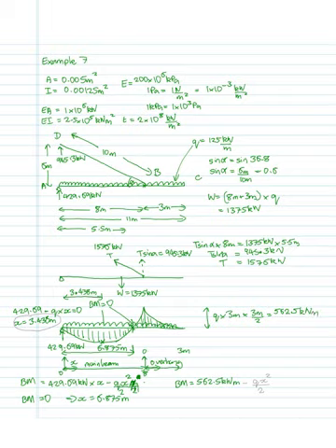So there should be a there, and that from there should be subtracted Q x squared over 2 to deal with the UDL acting over the overhang.